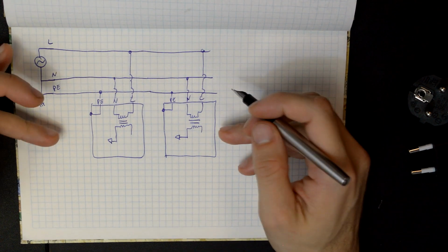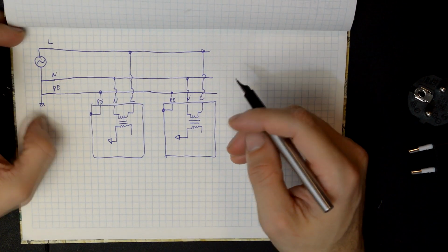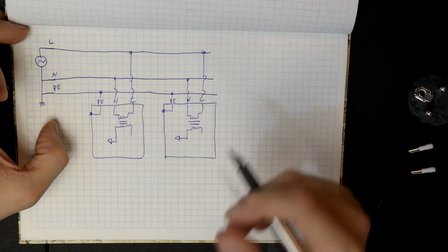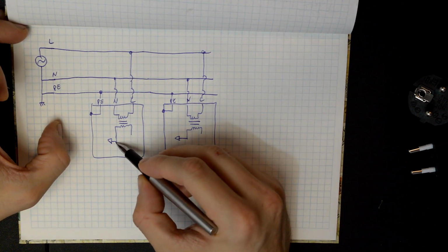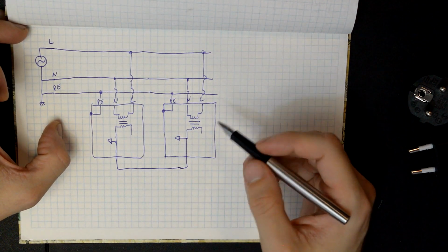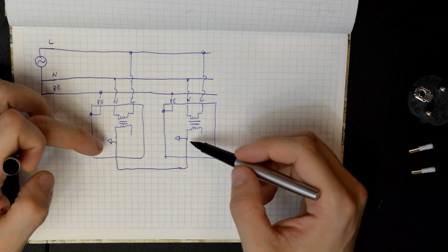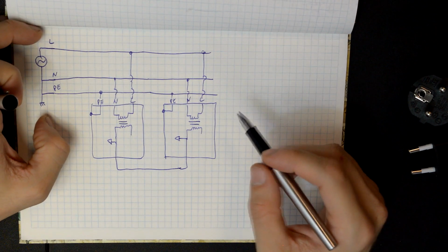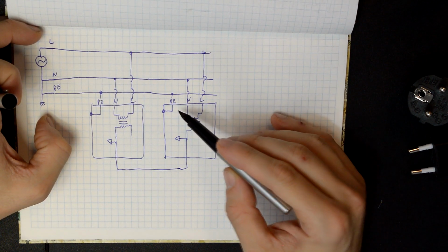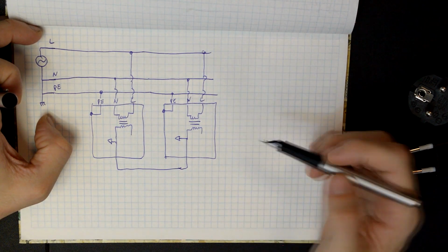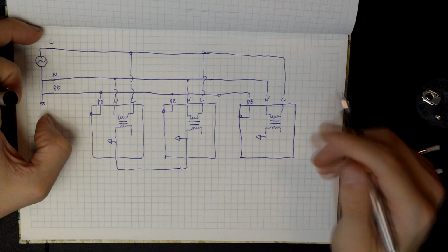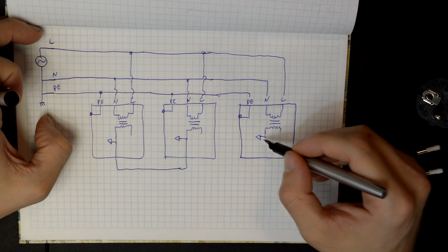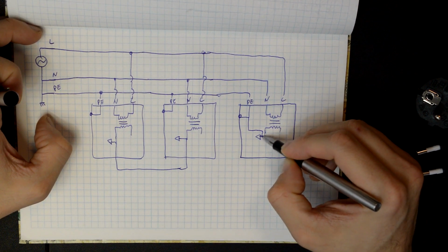Now if you have 2 units powered from the same grid, and these 2 units interact, like let's say your computer is sending audio information to your amplifier, then usually the ground is interconnected between these 2. And that's not a problem, since this local ground is completely isolated from the electrical grid. Now, as I said, in certain cases this protected earth is not really completely isolated. One device that is built in this manner is the oscilloscope. So normally every oscilloscope will have its local signal ground referenced to the earth ground.